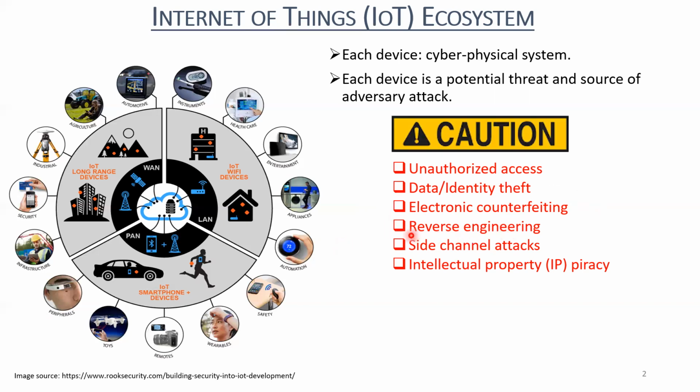Another problem, mainly in China, is reverse engineering. There are many companies in China that take these chips, etch and lap them layer by layer, and try to image them to make a 3D map of the circuit. Once they etch it layer by layer, they are at the same time also imaging it from all 3 or 4 sides, so that they come up with the exact circuit that is there.